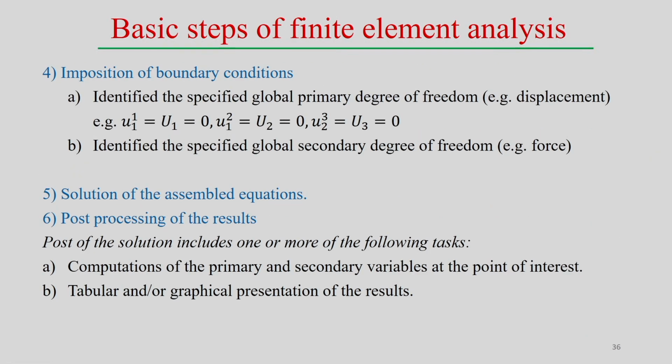Now, before solution, once we look into the governing equation, or maybe in a displacement problem also, it is necessary to impose the boundary condition. For example, in a strain displacement problem also. In that case, identify the specified global primary degrees of freedom, displacement, and for example, capital U1, capital U2 and capital U3 can be 0.